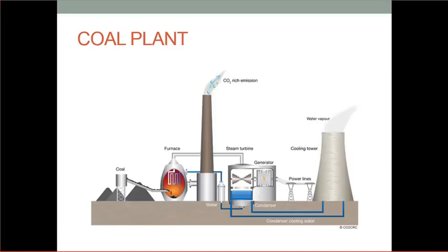So the emissions that we're interested in with coal plants, of course, SO2, right? Sulfur. And this is very simplified, because what really happens is actually kind of interesting. I can give you an example of the St. Johns River Power Park here in Jacksonville. They built that unit in the 80s. And the total cost for 2 units that make around 1,300 megawatts was right around $1 billion. Well, 400 million of that was for electric generation, actually making electricity, and 600 million of that was for emissions reduction equipment on the back end.